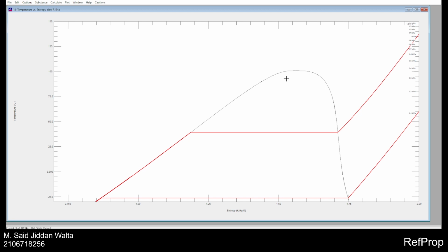And so what a typical vapor compression refrigeration cycle looks like is that it would start at this point in the bottom right, but the problem states that we are starting at a superheated state at the inlet of the compressor, so it is likely to be somewhere higher up here, where the compressor would isentropically compress the refrigerant, raising it to a higher temperature directly above this point.